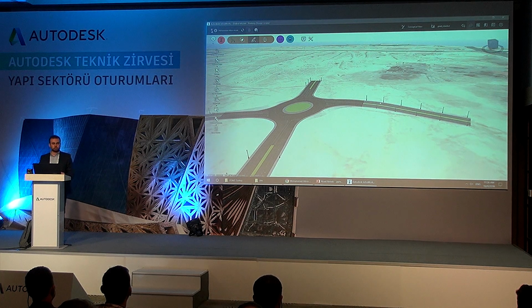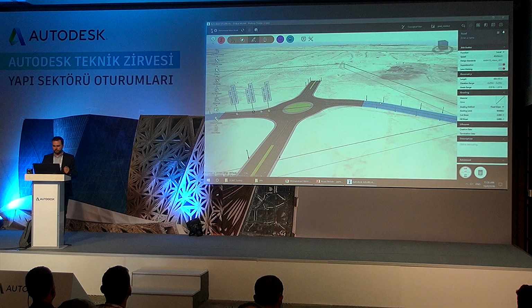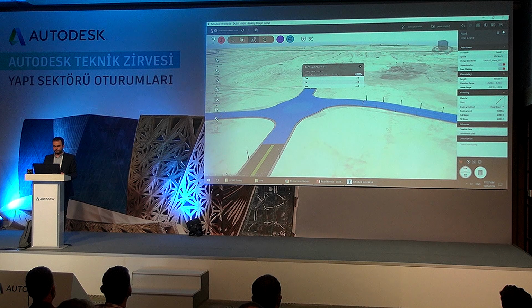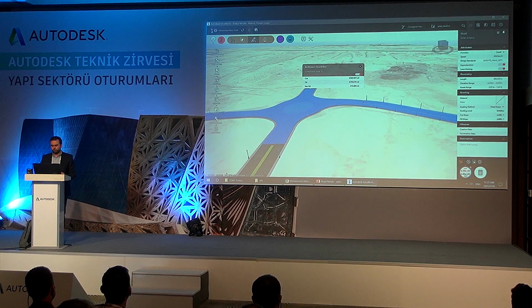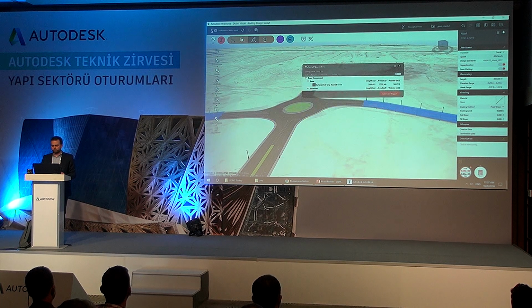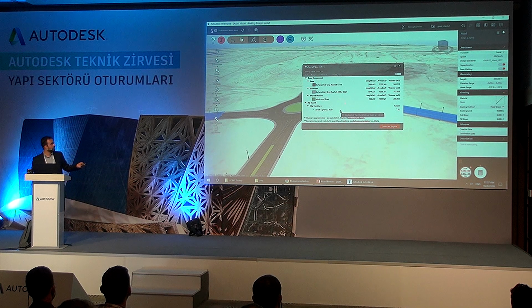So I just click on that road, and again, I'm using component roads, not planning roads. We go to this cut and fill. Once we click on the cut and fill, it asks me, do you want to calculate for the whole length of the road? I say yes. And then I hit this button. And there you go. All the quantities for cut and fill and the net fill are calculated. If I hit the calculator button, it's going to show me all the ingredients that make up this road, including the street lighting poles estimate of maybe, I can't see it, it's like 52, which then I can generate to Excel to a cost report.